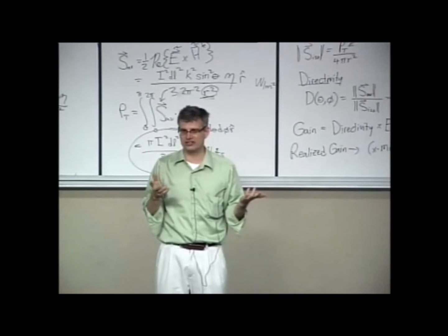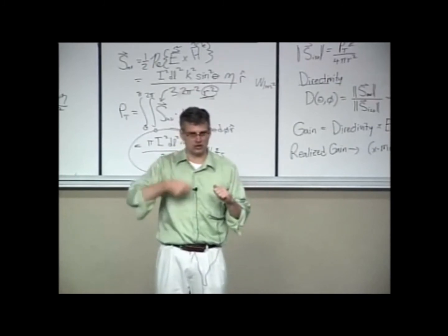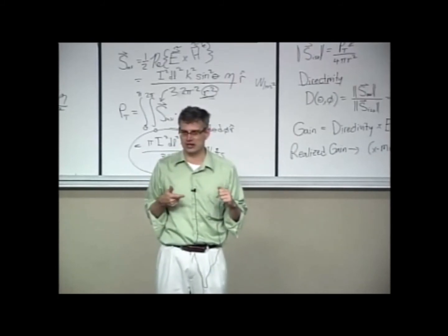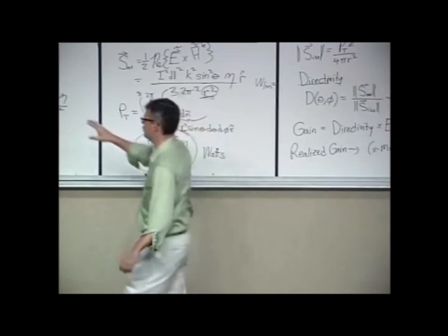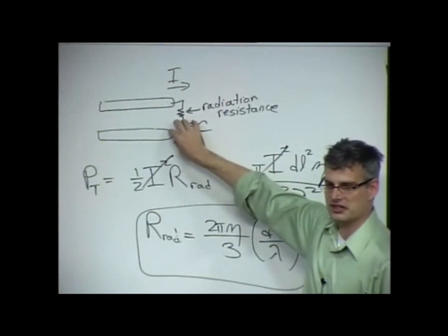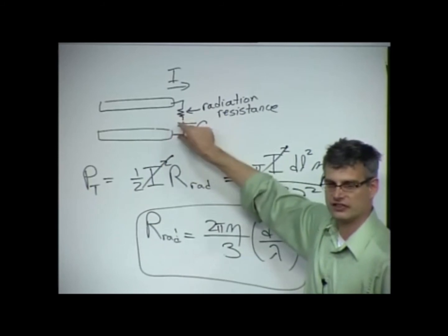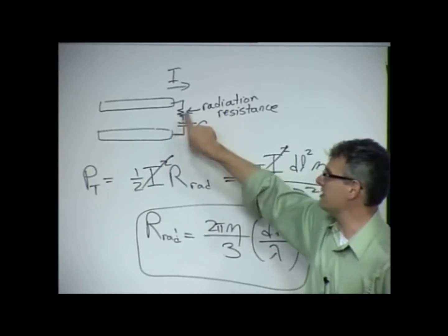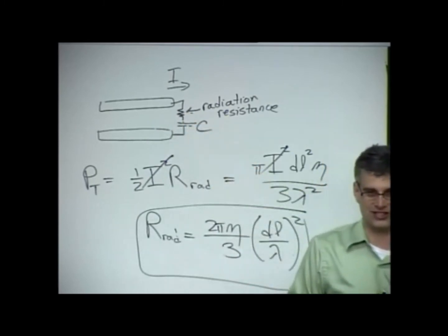They tend to be relatively low Q, right? The more inductance you accumulate, the more series resistance you accumulate as well. So even if I could get rid of this capacitance with an inductor, I'm going to leave a little bit of resistance in the circuit pathway, which will wind up being much larger than my radiation resistance.